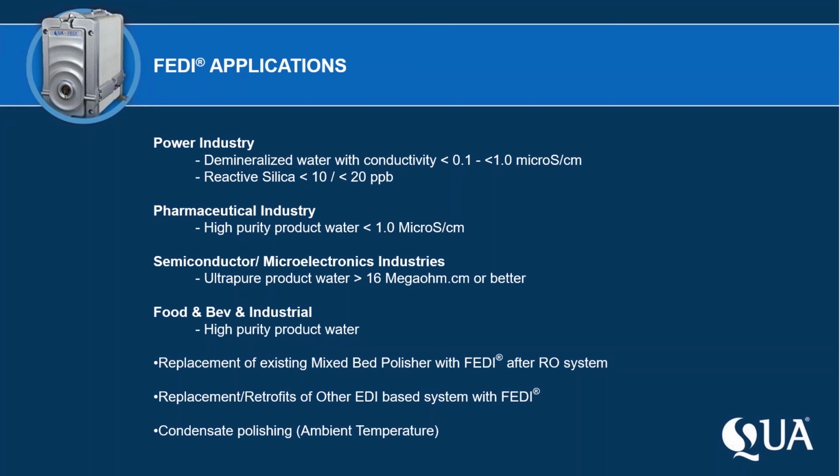So they were probably the first to welcome EDI because it was a technology where they didn't have to swap out ion exchange bottles. It produced and exceeded the pharmaceutical requirement specs for TOC and microsiemens. So they liked it because you could bring it in, you validated it once, and it made continuously high purity water that exceeded their specs, and you only needed to validate it once.